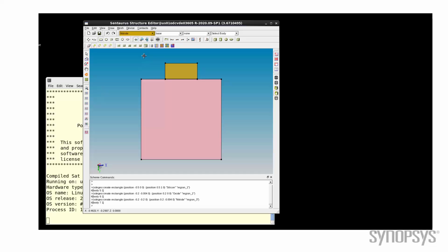This is also a good time to comment on Boolean overlap operations. When creating a device with multiple regions in Centaurus Structure Editor, later added regions might intersect existing regions. If this occurs, a predefined scheme is used to resolve the overlapping of the regions. To select the overlap resolution behavior, choose Draw Overlap Behavior, or click the corresponding toolbar button. The default overlap resolution behavior available in Centaurus Structure Editor is New replaces Old.